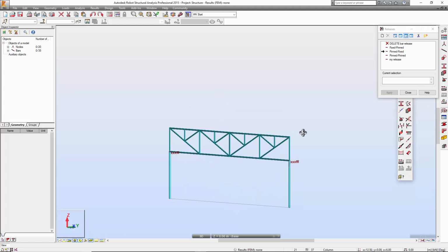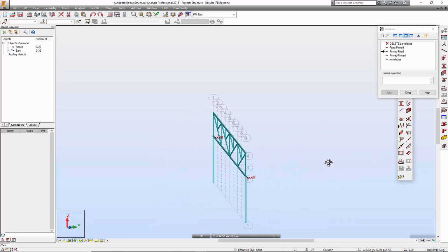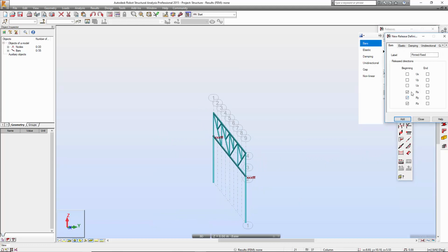So now since we have done this one, the column with a pin release in here, however, don't forget this moment we got trouble because let's have a look at this structure. What we released is the starting point where we drew the structure, the column from this point to this point. So the starting point, the head of the column, has a 3 direction release. Is it going to be a stable structure?